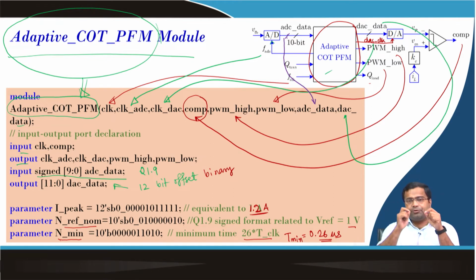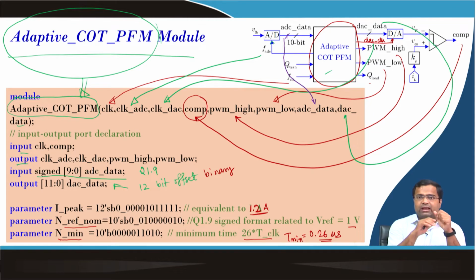That means, if you take that signal and this is an IO pin, it may not have sufficient current driving capability, and if you use that pin to drive multiple circuits, then this pin may not have sufficient current to drive, because if you use just comparator 1 or 2 block to trigger, that is fine, but this comp will be used multiple times inside.